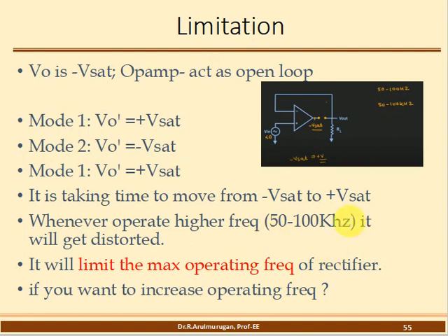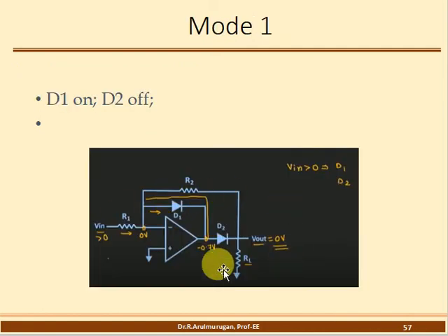The one biggest limitation you can say is that it does not operate at higher frequency; it gets distorted. Then what to do? That's why you can go for the precision rectifier.